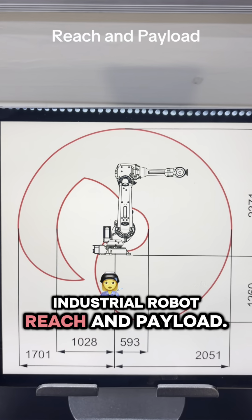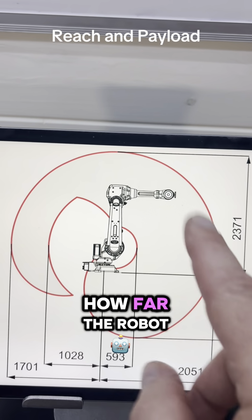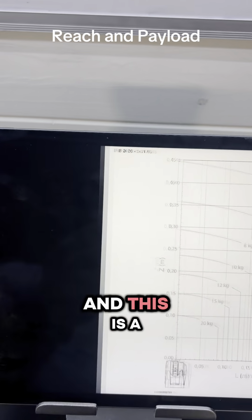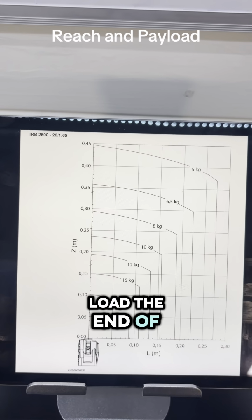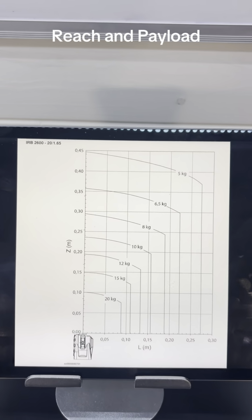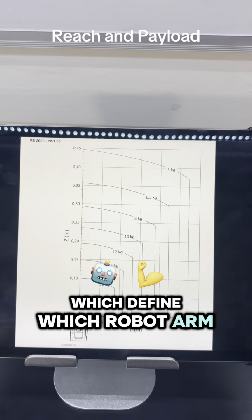Industrial robot reach and payload. So that's a reach diagram. It's showing you how far the robot can reach. And this is a payload diagram showing you how much load the end of the robot can carry. These are the two things which define which robot arm you need.